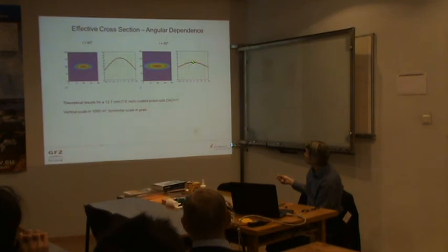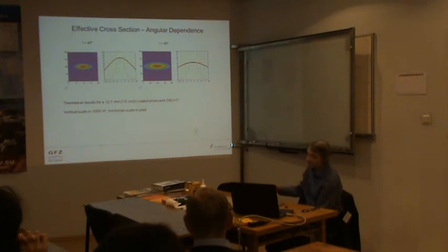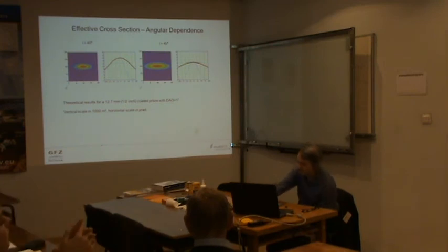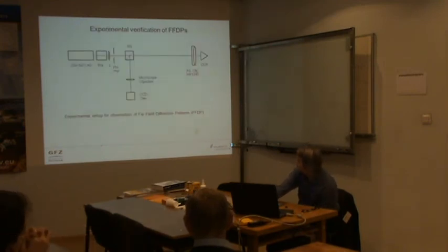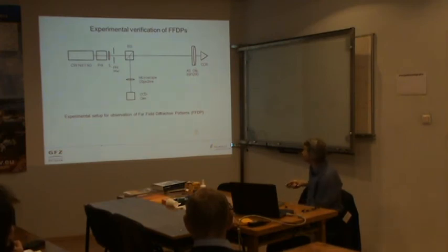And you see from 400,000, we have come down to about 6,000, meaning already 100 times less in case we incline the prism to a large degree, and we lose signal again. All this, because you cannot always assume that your light is going perpendicular into your reflector, gives rise to the losses. A few words on how we can verify what I've told you here.